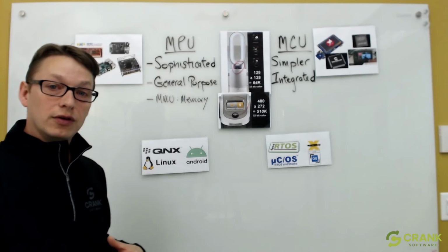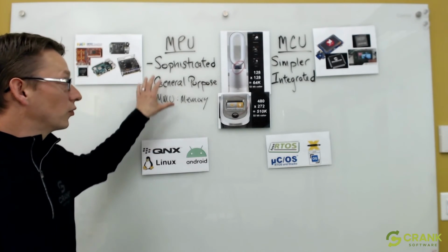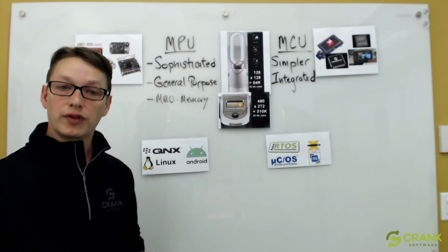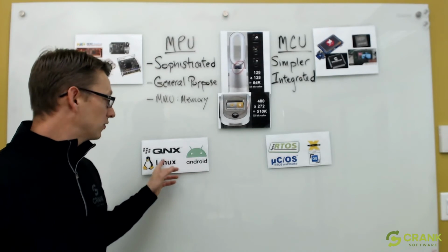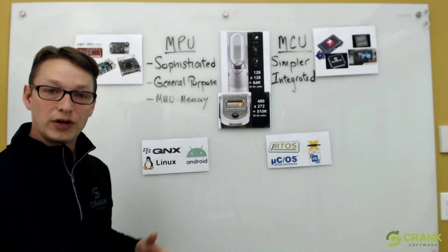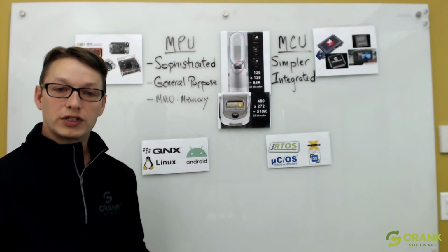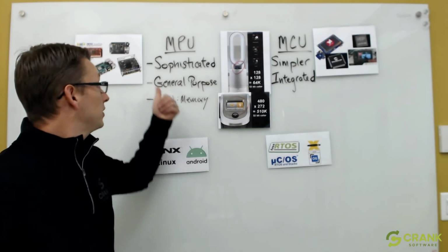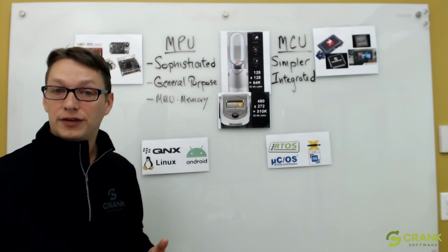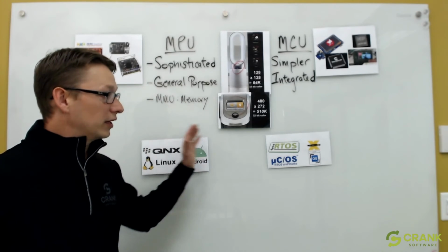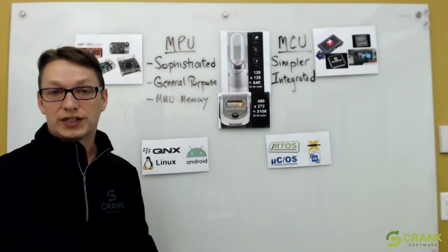But maybe on a higher-end system where there's more functionality, more integration with other componentry, you might be using a Linux system or QNX system as an operating system base to give you more technology access. And you might be using something like an i.MX6 or an i.MX8. The same design can flow back and forth if you choose the right technology.